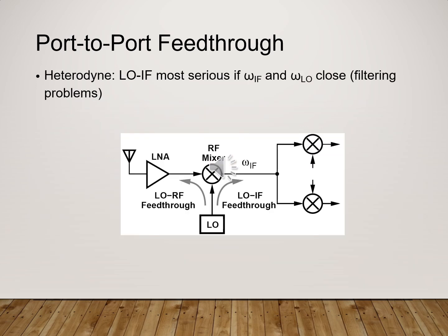In this slide, we show that we can still get local oscillator feed-through if we take a single-ended output as shown in the figure, or if there's a DC current in the signal path. There's often DC offset present, since the output of the transconductance amplifier will have DC current components.